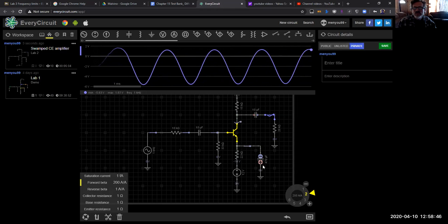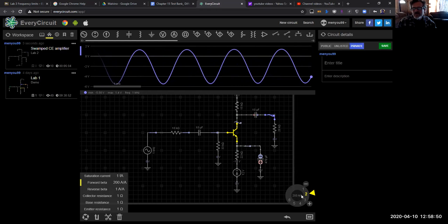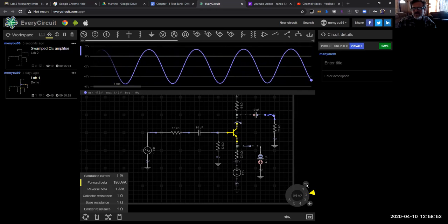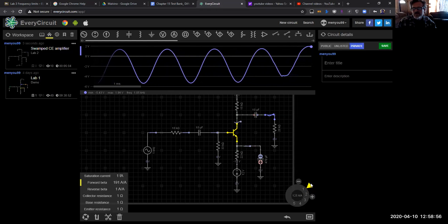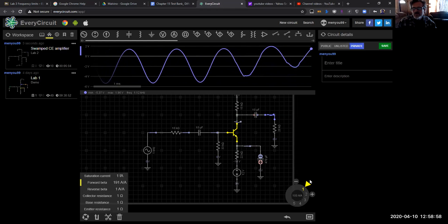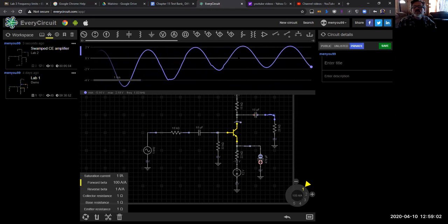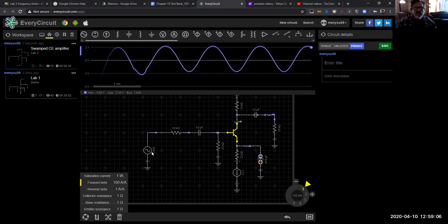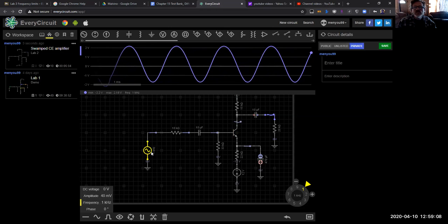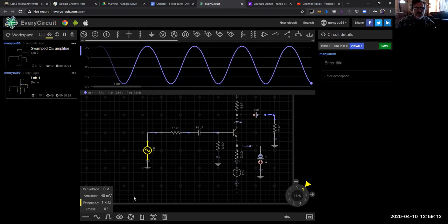So we would have to actually play with the values of our emitter to balance out, according to the beta value of this. But if we pump it back up to a stable area here, we assume a beta of 100, and now we've got a nice crossover at 0, 2 up, 2 down. I'm only putting in 40 millivolts, like it said, but sweep through and take a look at these things.